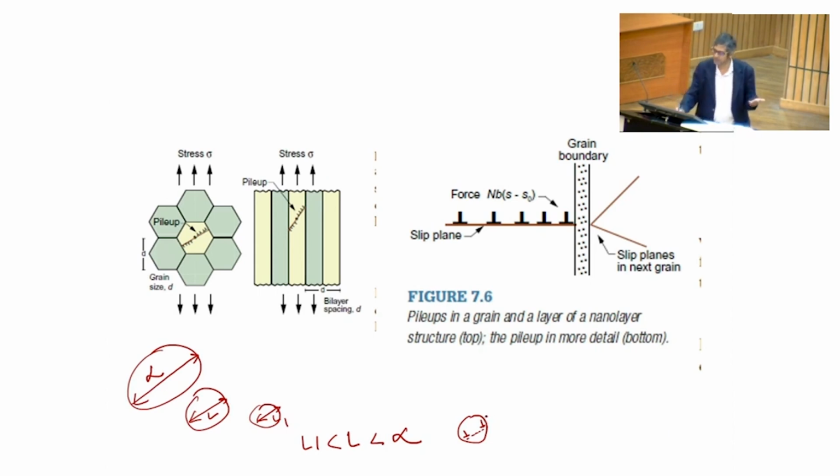Because the amount of stress applied on the grain boundaries will be much smaller. Even you can have a grain size which is much smaller, where you can only have 1 dislocation. There, this dislocation is comfortably sitting inside the grain without even interacting with other dislocations. So therefore, there will be no force acting on the grain boundaries.